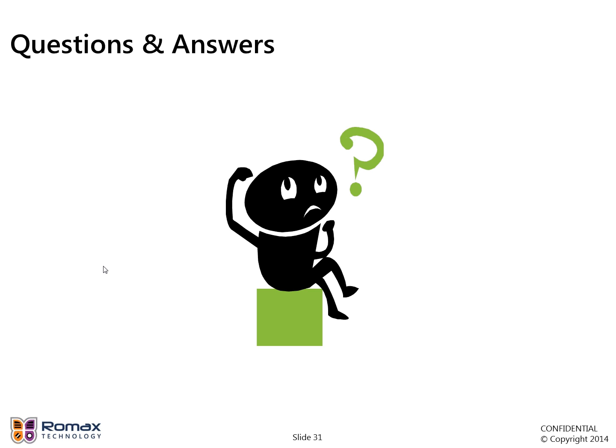So this is done, I can't give you details of the algorithm because it's proprietary, but this is done using an optimization process which works out how many degrees of freedom you need, how to chop the model up, where those bodies need to be positioned, and how they are connected together. And it's a multi-step, iterative process that runs very quickly, so that in a few seconds we get this model that is optimized in terms of the smallest number of degrees of freedom and the simplest possible model that will meet the requirements of the frequency you specify.